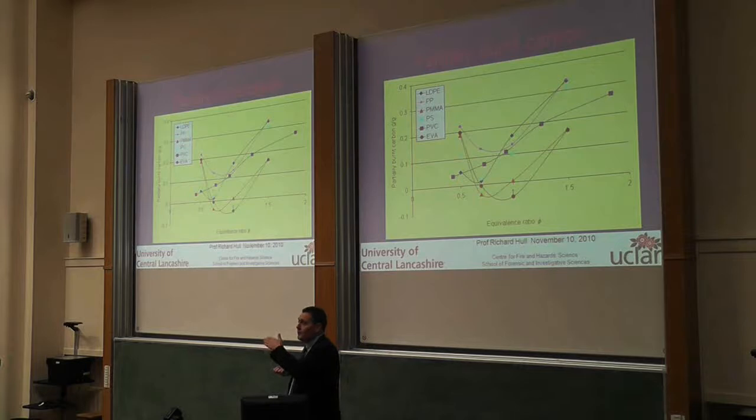the amount of products that are oxidized in the secondary oxidizer, the bits of alkanes, alkenes, soot, goes up from 0.5 to 0.7 upwards as a product of incomplete combustion, in just the same way as the carbon monoxide goes up, with a yield in grams per gram from practically 0, or even in some cases we had more CO2 in the mixing chamber than we did in the secondary oxidizer, perhaps as a result of instrumental error.